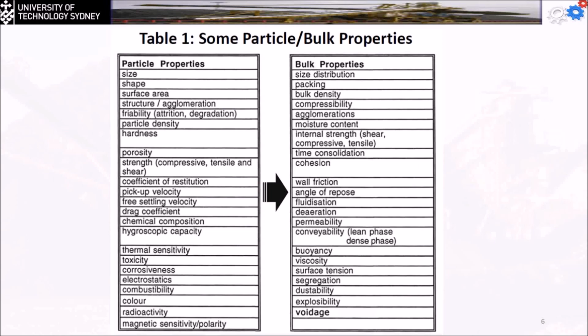So you know what the term density is, right? It's the mass divided by the volume. Now, if I'm going to have the bulk density, that's the actual mass over the actual volume I have. But for the actual density, I have to remove the spaces and consider this the new volume. That's why the actual density is usually going to be higher than the bulk density.